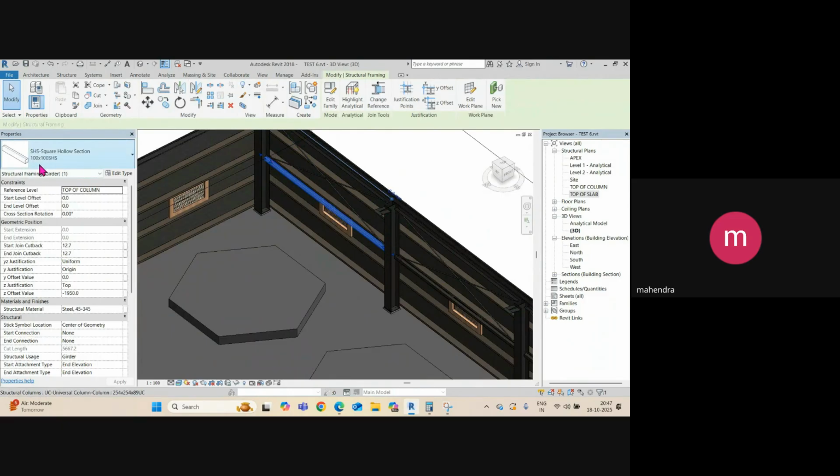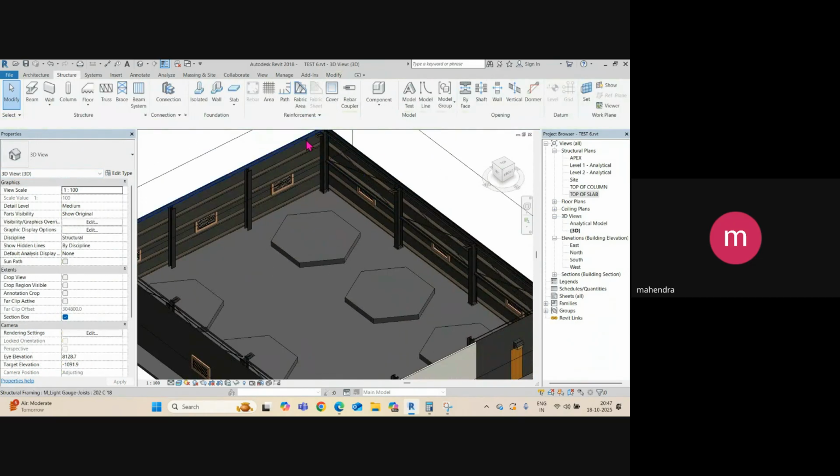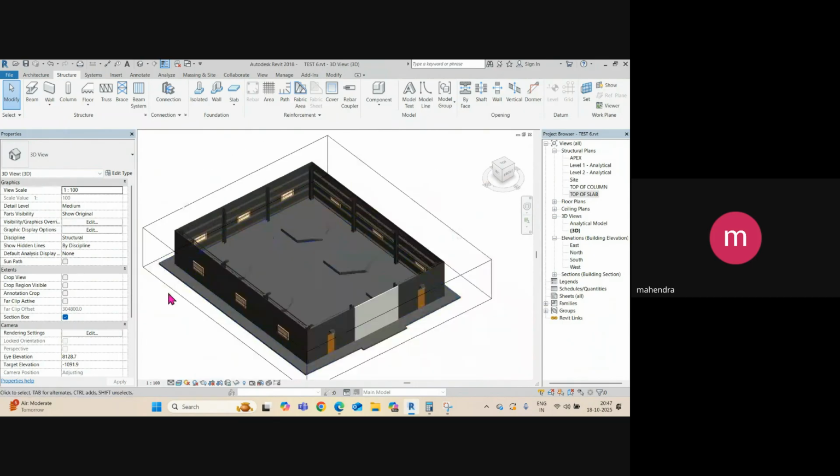So I will assign the beam B1 for 100 by 100 SHS. Then purlin P1, P2, P3, then side girts. You can just give the side girts. Mostly we are adding S1 side girt, S2, S3. And then fascia purlin we can add PC1. As per your requirement, you can give the annotation, and then we will add the table,